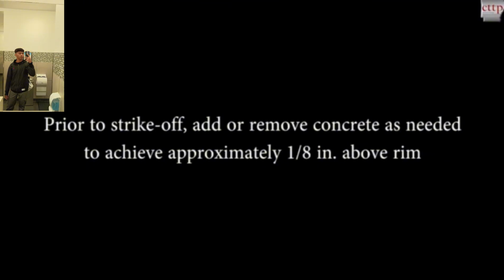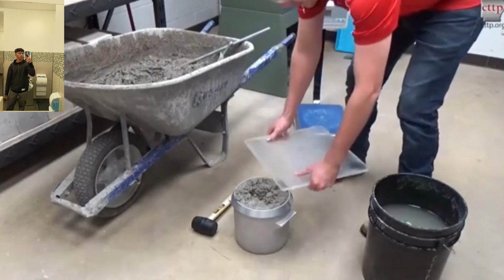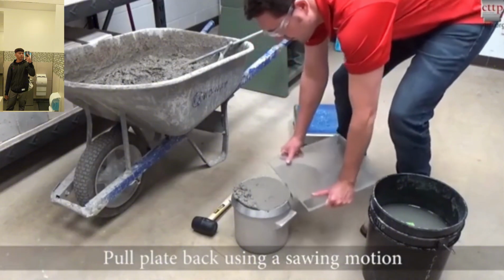Prior to strike off, add or remove concrete as needed to achieve approximately 1/8 inch above the rim. Cover 2/3 of the measure with the strike off plate. Pull the plate back using a sawing motion.